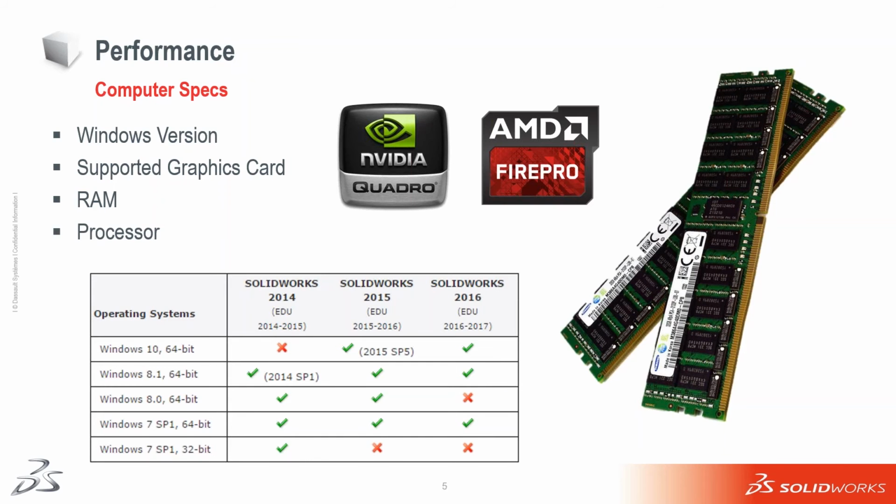With the RAM, SOLIDWORKS recommends 8 gigs of RAM on any workstations running SOLIDWORKS. We typically recommend go ahead and shifting up to 16 gigs. I know in our training room, we were running 8 gigs on each of those workstations for a while, and even just doing some simple training files, no crazy multitasking or heavy workflow that you would get on probably your everyday basis. But we did go ahead and upgrade those to 16 gigs, and that 8 gig to 16 gig jump with RAM really is very noticeable. More noticeable than the 16 gig to 32 gig jump.